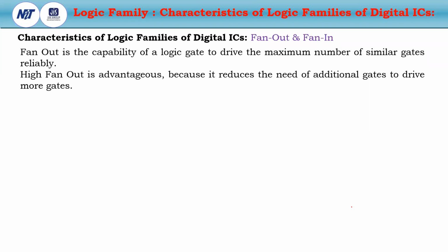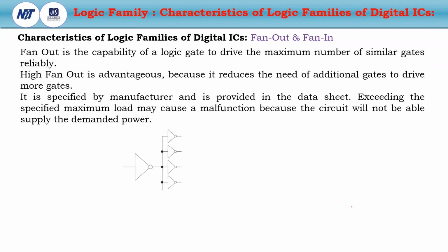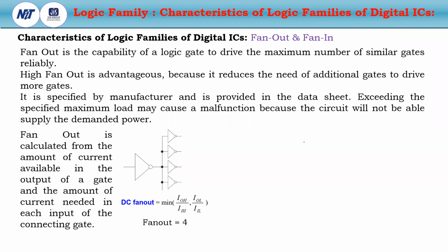High fan out is advantageous because it reduces the need for additional gates to drive more gates. Otherwise, many power supplies would be required to drive these logic gates separately. But if the fan out is maximum, then one logic gate can drive other logic gates.